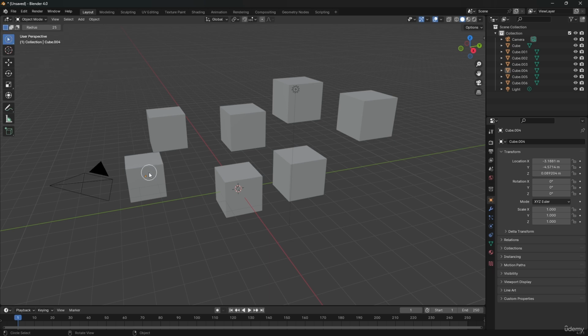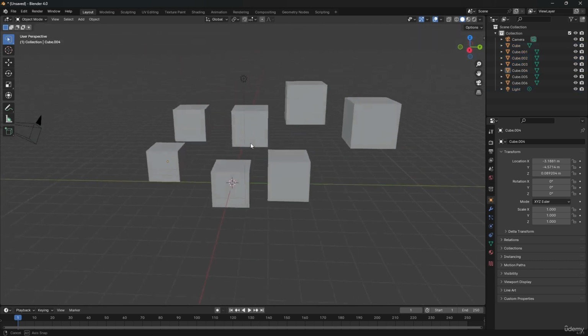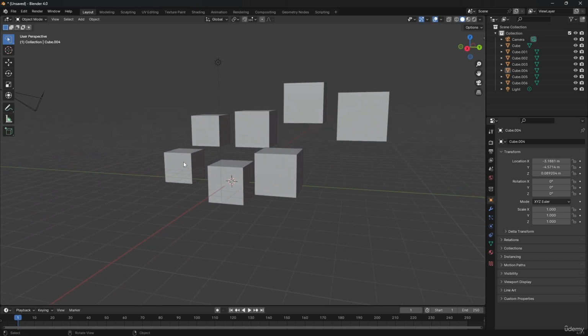With this you can simply left click and hold and drag over objects to select them. And finally we have the lasso tool. Now this lets you create custom shapes for selection. This is helpful in cases where you want to avoid accidentally selecting certain objects. So if I don't want to drag over this, I can simply left click and hold, and you can see it creates my own custom shape for making this selection.